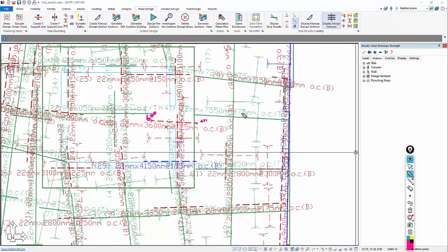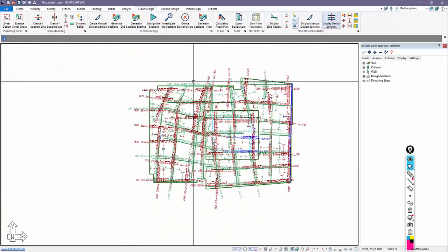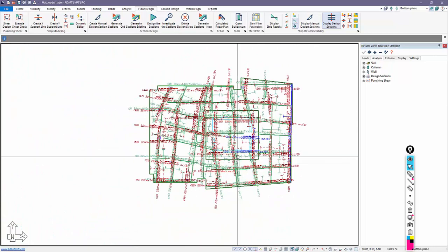So if we look at a cut through there, if this cut looks something like this, and that bar is intended to be relevant relative to the effective depth from this slab upward, then there's a chance it could be sticking out of the slab below the 450 millimeter slab. That's why it's indicated as blue. It's really just a warning to the user, check those bars for detailing of the bar or placement of the bar. Okay, so these are the reinforcement outcomes for the strips.